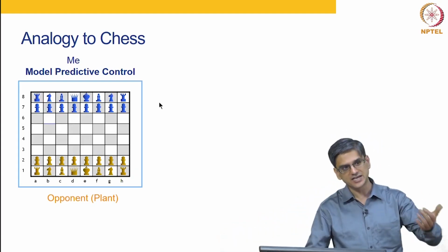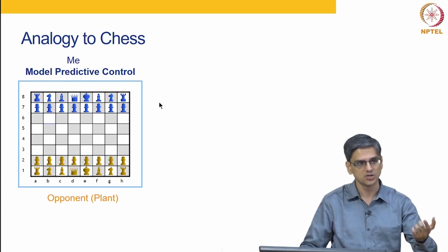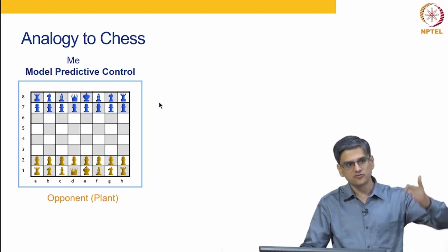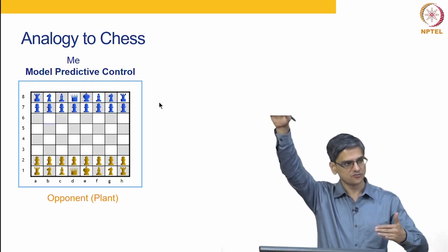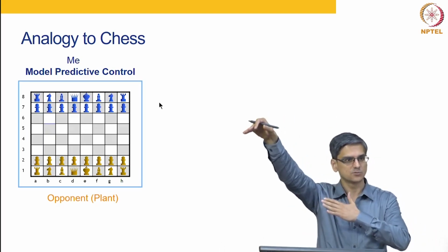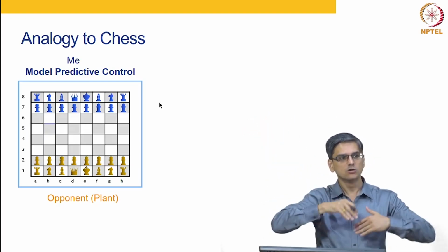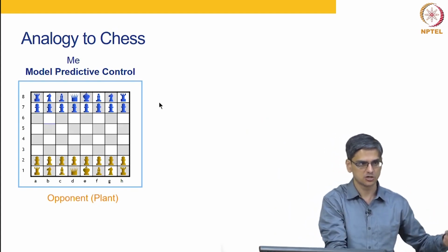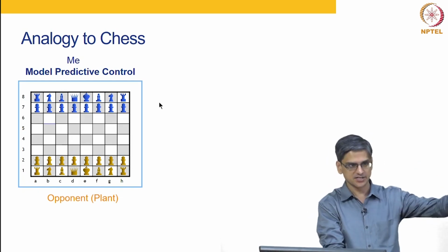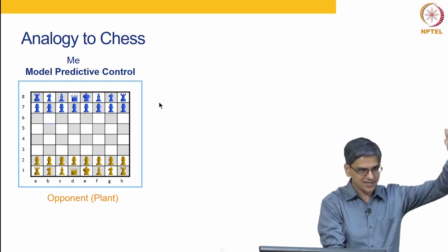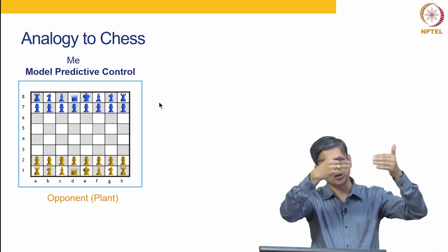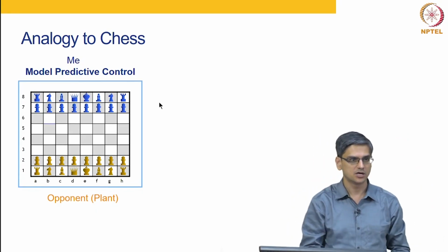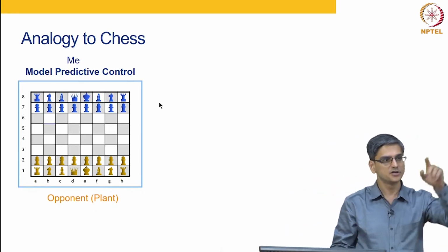If you only allow prediction for a long time in the future, but manipulation only for one time step in the future, it is going to move in the direction that will take your future where your set point is. But if you allow 5 time steps into the future to change your input moves, it will go in the opposite direction, and then as the system starts responding, it will immediately come back, and you will see examples of that happening in week 4. Did you have a question?